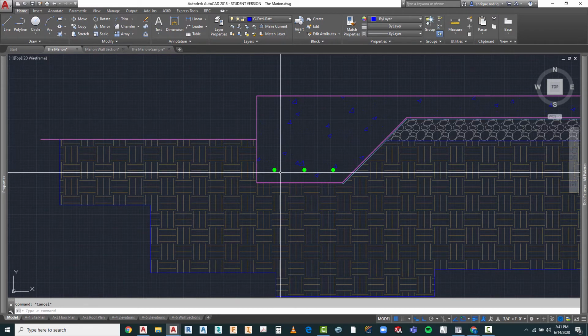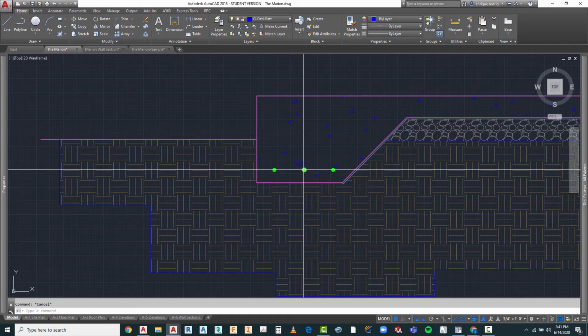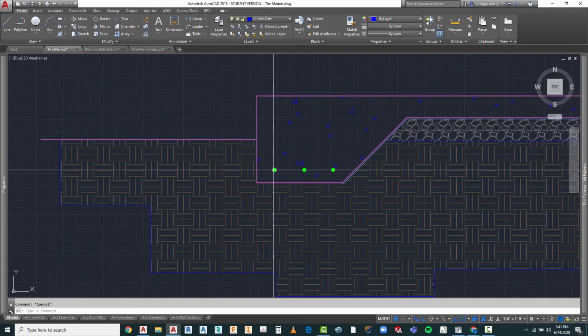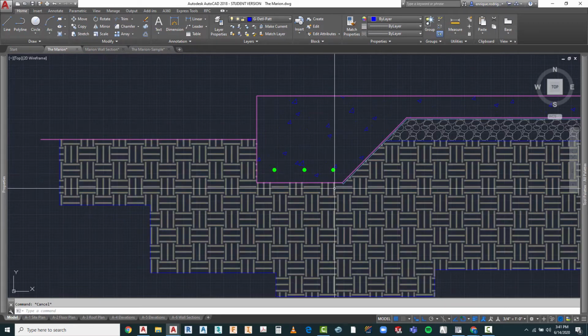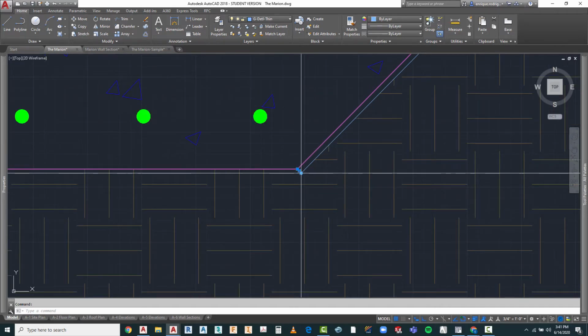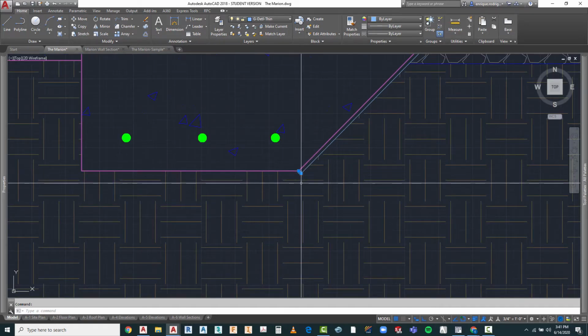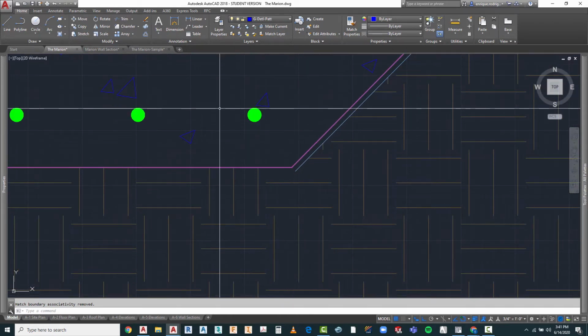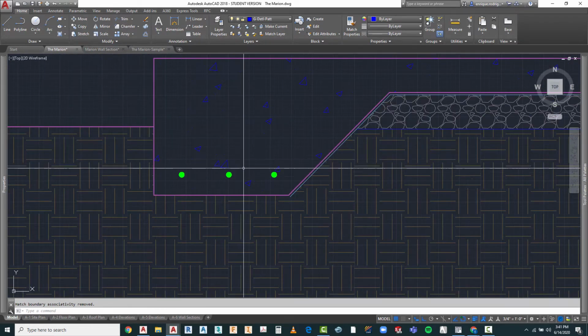So what you're looking at is the end section of a cut through. So these are called horizontal reinforcing. There's a certain amount of concrete that you need all the way around them to provide what we call cover. And the reason I shut this off here before is because I did not want this hatch pattern to sneak its way into there. So we've got that reinforcing bar.